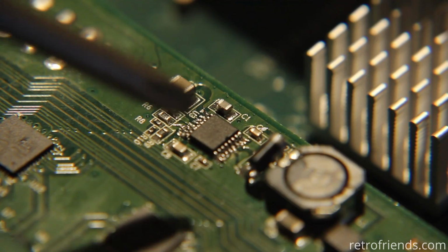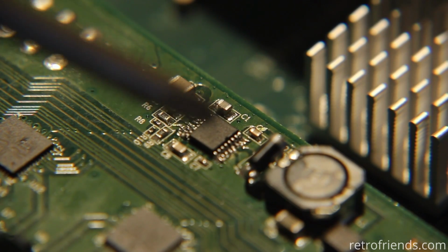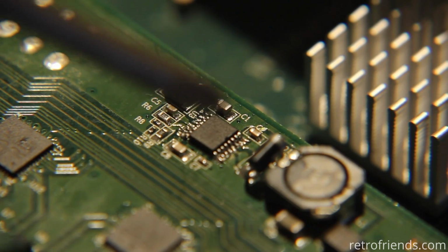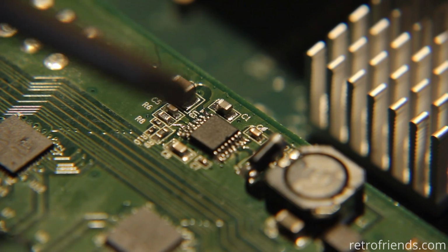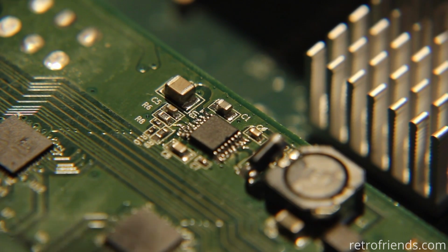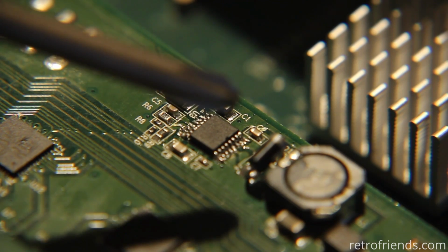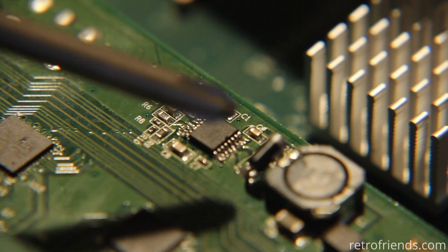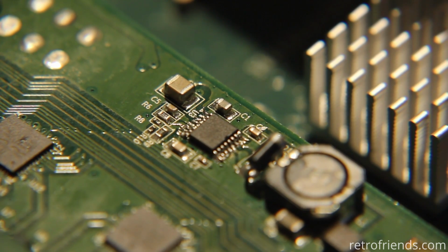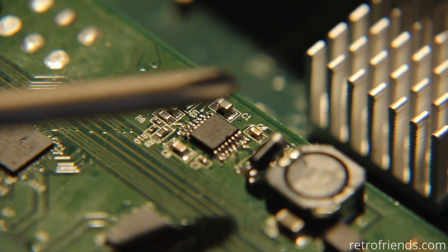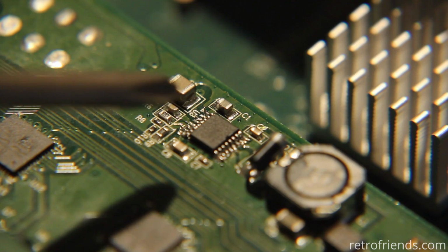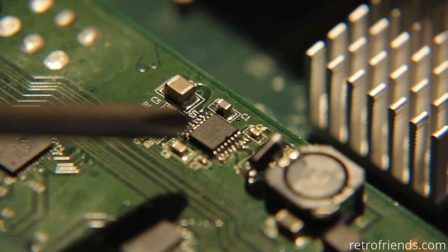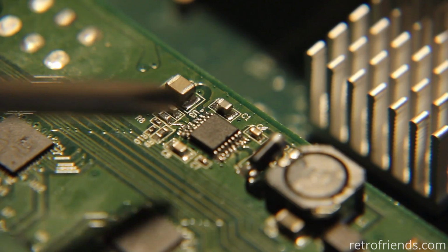Anyway, finally got it in. I went ahead and tested continuity to make sure I wasn't shorted between the pins, and a couple of pins were shorted that shouldn't have been. Well, there were several pins that were shorted that shouldn't have been. But one of them goes over to a diode that was right next to it, and that diode was completely internally shorted.